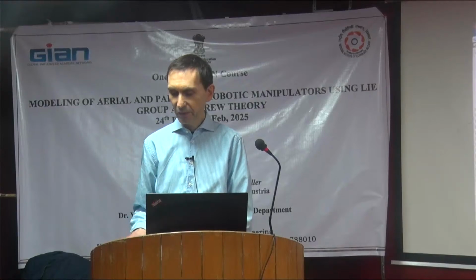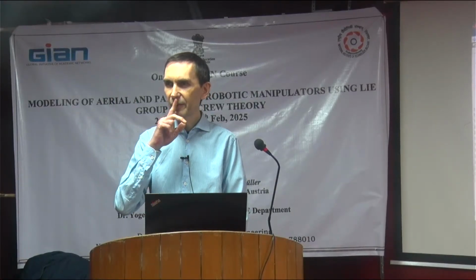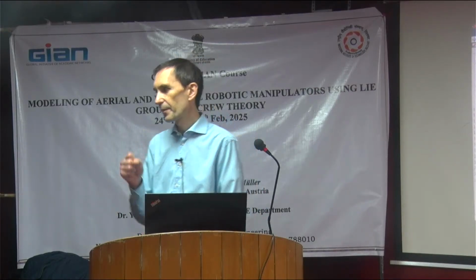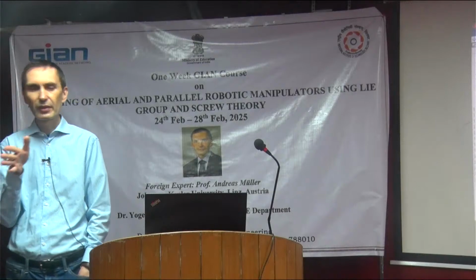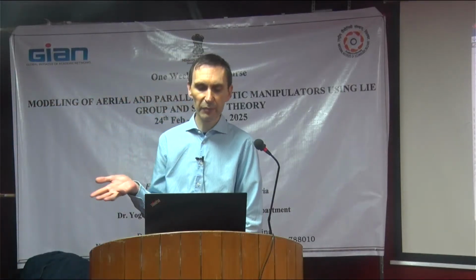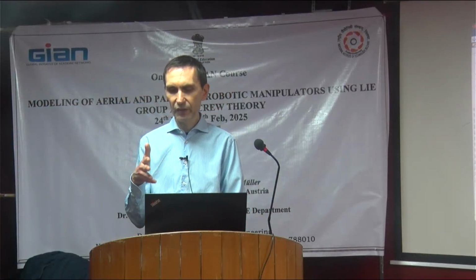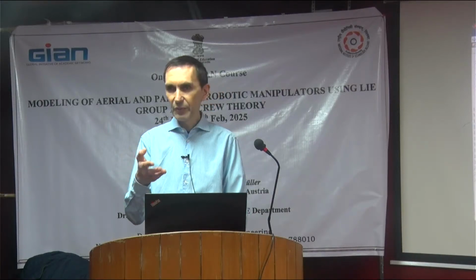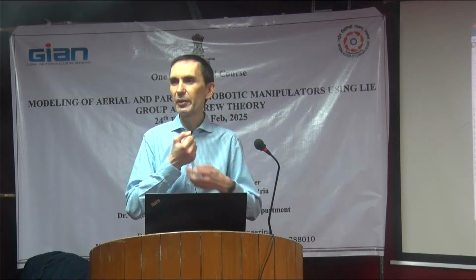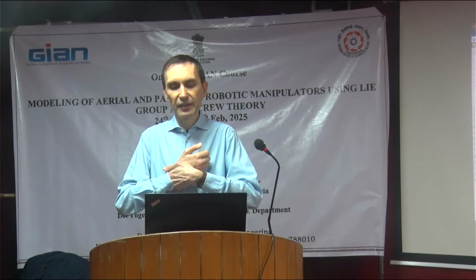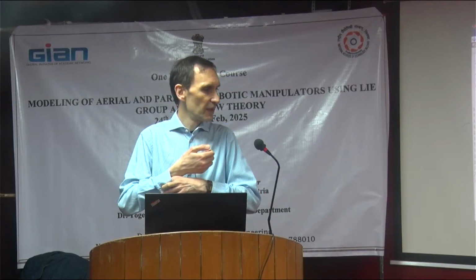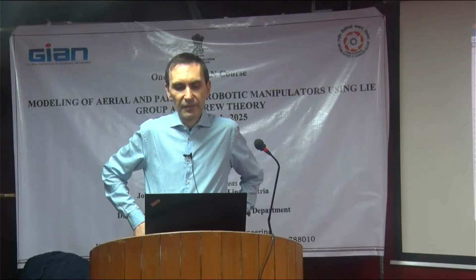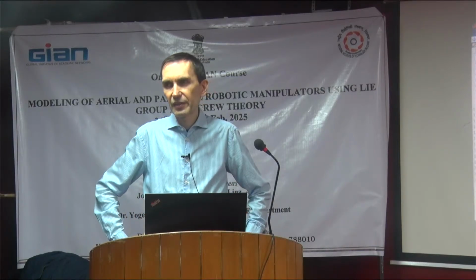I think you weren't here yesterday when we talked about it. It's more like a convention. Mathematically you can prove that it makes sense in line geometry to say this must be an infinite pitch. So we have the two extremes: the 0 pitch is a pure rotation. Then there's a finite pitch, which is a screw motion, and then we have an infinite pitch. An infinite pitch means that you need an infinite translation in order to achieve rotation.